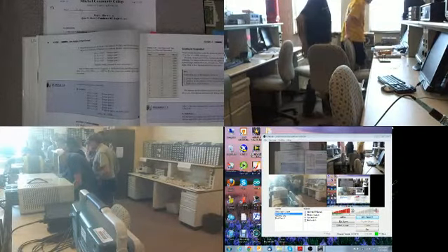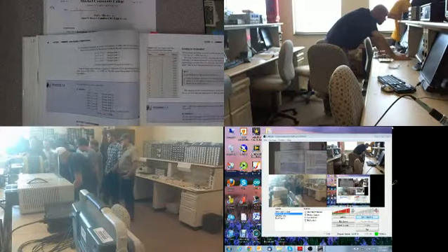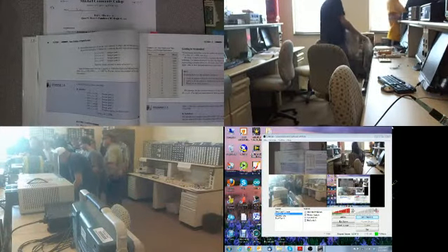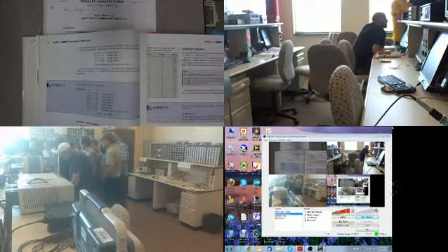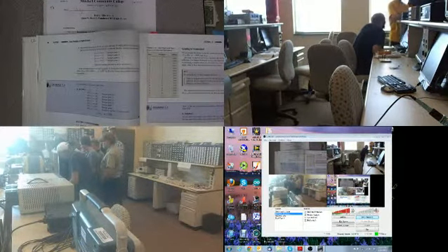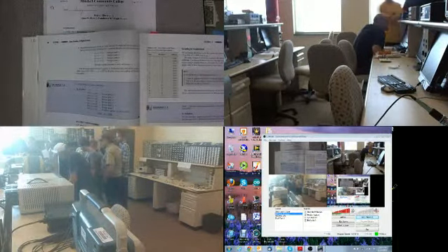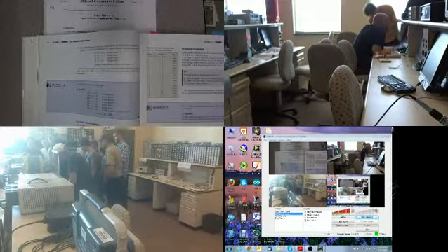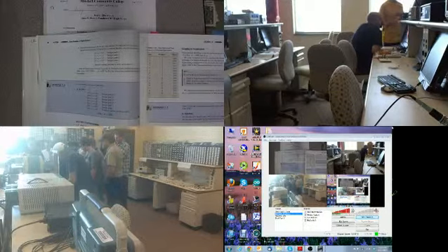Do you mind if I draw on here? Okay. So it says number 5, make a logic diagram including pin numbers, part numbers, and chip designators, U1A, that creates a 3-input OR function. This shows all your gates that you have over here on page lab 1.